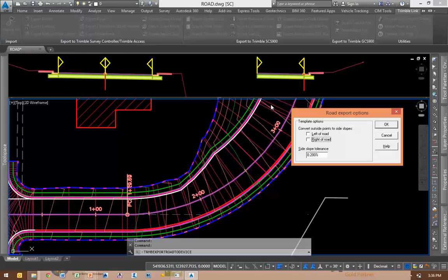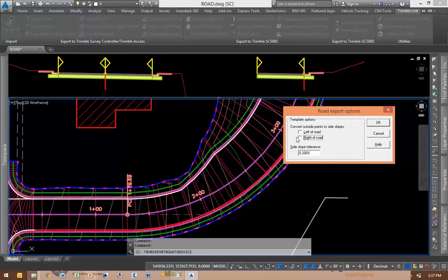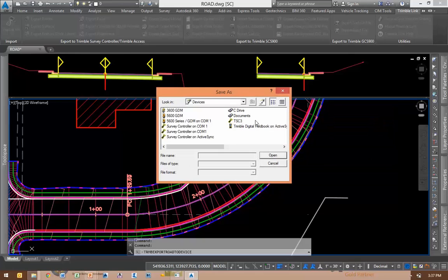Where it can be advantageous is if you don't have any targets except for surface targets. Because what it'll do is it'll put you in like a slope staking routine, where it'll take the slopes as defined in here, 2 to 1s, 10%, whatever it might be, and it'll calculate the actual catch point in the field, not the grading limits as I've virtually designed in here. Okay? So you want to hang on to your targets, leave this checked off. Basically leave it checked off all the time.